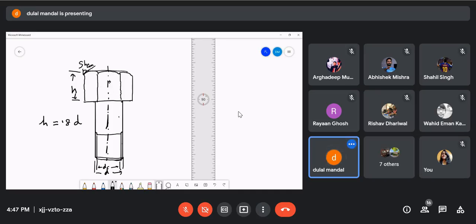This will make it almost round. If you suppose the number of faces is 20, this will be almost round. So if you use a spanner or wrench, the contact surface between these two will be very small, so you cannot apply a certain torque on it. That means you can apply the torque, but the torque will not be transmitted to your bolt. So this number of surfaces cannot be increased.